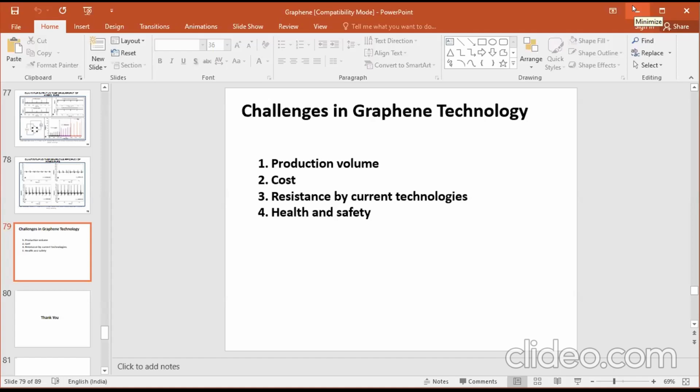That's what I understood, because there is work going on with cement and graphene. They have added graphene to the cement, right? Basically, they want to improve the compressive strength of the material, the overall bonding between the steel and the cement, and also the bonding between the aggregates. There is literature on such studies. It's definitely possible to make cement composites using graphene with improved properties. But the cost will be high, so that will be one of the challenges.